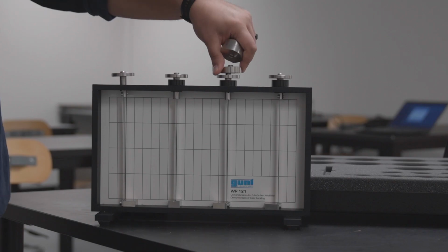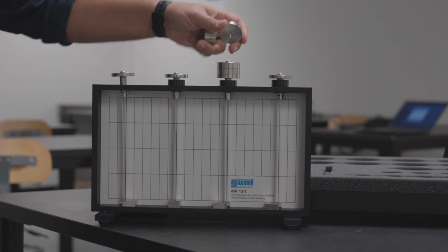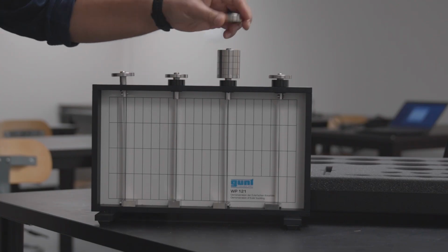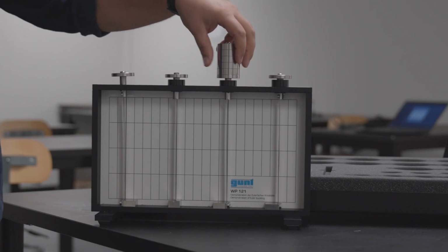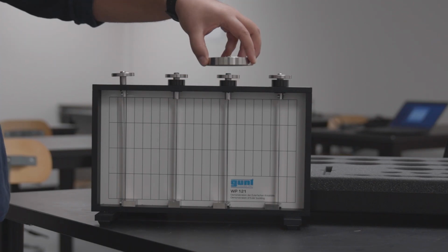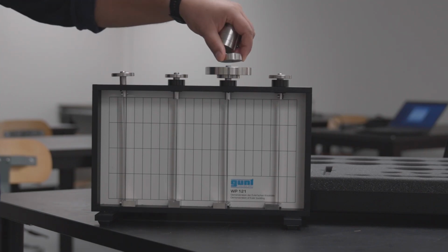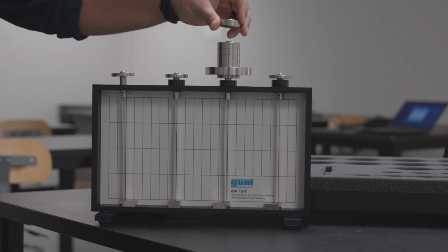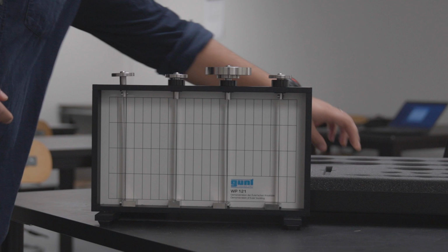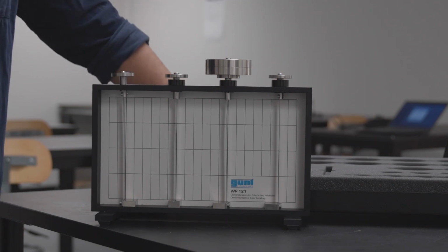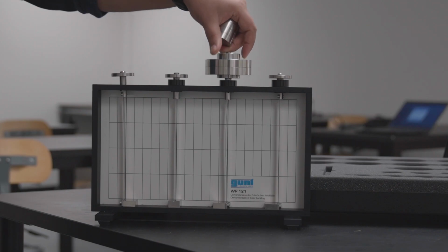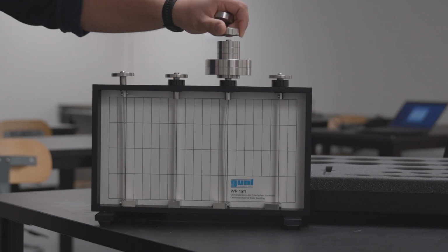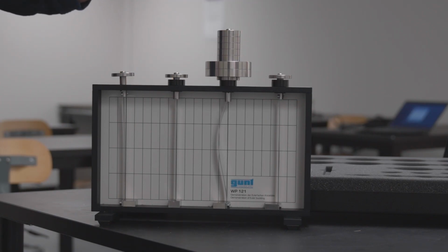Let me add the loads to the third one as well to give you an idea of the buckling load. Again, you have to add loads 1 Newton by 1 Newton. You should not jump to a 5 Newton load because you want to be as accurate as possible. Ten Newtons now. Going to remove this and add another 5 Newton load. I think this is going to buckle at 12 Newton or 13 Newtons. We'll see. Did not buckle at 13. It did buckle at 15.